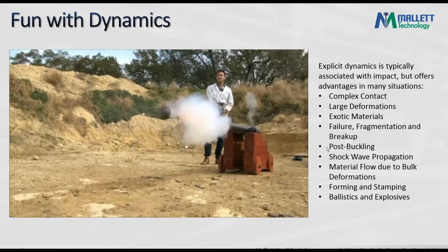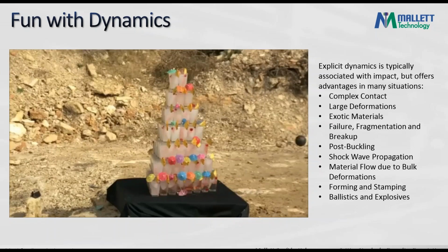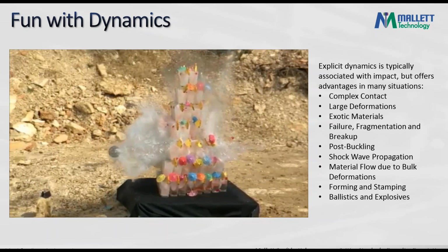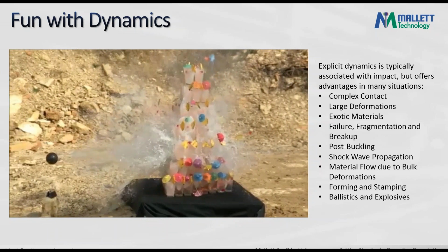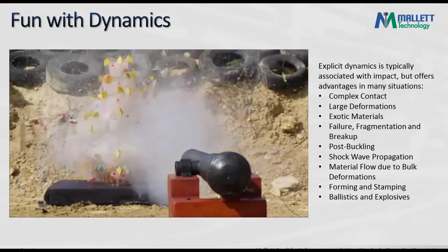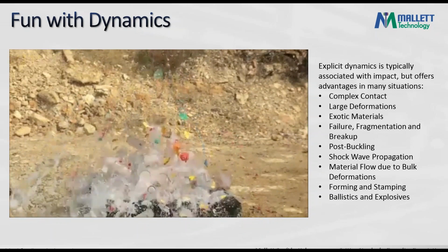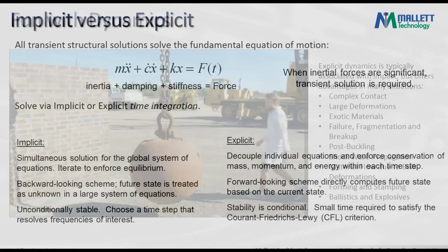Even in simulations that we might be tempted to use ANSYS, we often make a choice to use Dyna to capture body-to-body contact because the explicit solver just carries significant advantages for stability and ease of use for that kind of problem.